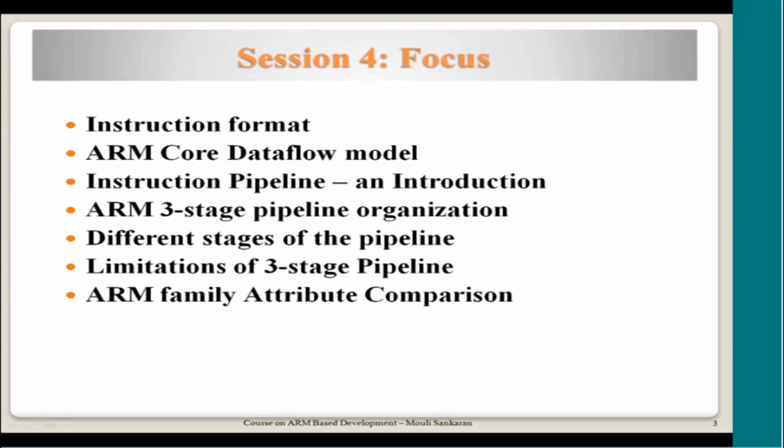What I mean by data flow model is that when an instruction gets decoded inside the ARM core, how a particular instruction gets executed by interacting with the different registers in the register file, and then sending the result back out to the register. And then we will touch upon the pipeline.